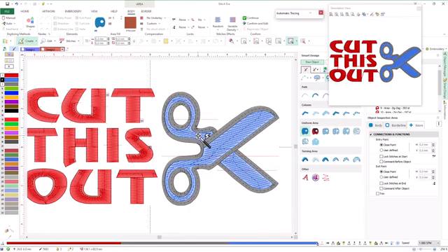If we review our design, we notice that we made a mistake in the sequence we followed to create the objects. We should have digitized the uniform areas of the scissors body first and then the edges. This is the usual way to do it since we get a much better finish. Let's adjust this sequence using the document map.